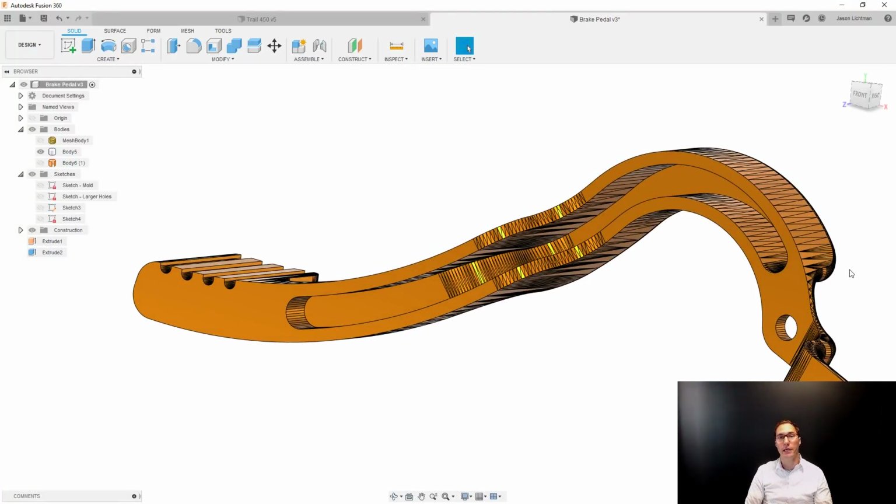So this was technique number 2, convert your model to a BREP. Again, you're limited to 50,000 triangles, but this is a great technique as long as you have models that are less than 50,000, or you could remesh your model. You could also split your mesh into multiple pieces that are each less than 50,000. You could then convert each one and merge them all together, but just be warned that the more BREP faces you have, the more processing it takes from your computer, and eventually that is going to slow you down and you're not going to be very happy.